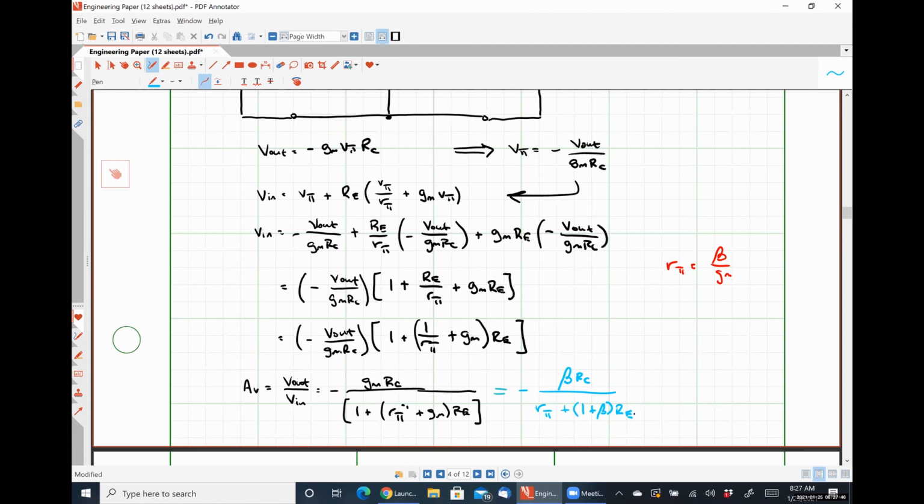So this degeneration scheme, for the biasing circuitry, we saw that it increased stability. For our amplifier scheme, that increased stability comes at a cost of lowering our voltage gain, all right? We're going to revisit this concept in a little bit and try to figure out if it's possible for us to effectively only degenerate our bias circuitry. And there is a way to do just that. But before we do that, let's explore what happens if we have this exact same circuit, but we include a base resistance as well.